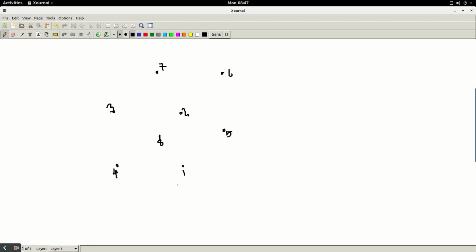Okay, so that tells you now that if you want to make a cube out of it, you need to join the faces. So one of these faces can be 1, 2, 3, and 4. Once you join them together, you have a face. So that's why you need to write a line like 1, 2, 3, 4. Over here, you have another one, 5, 6, 7, 8, but that's the back face. So if you do it counterclockwise on this side, that's going to be wrong. It has to be clockwise because that's the other one.